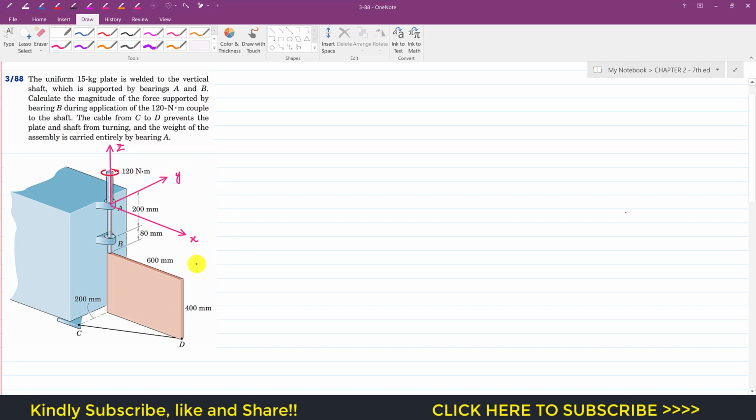Now the first task in this problem is that we have to find the Cartesian vector representation of the tension in this cable. So let me represent the tension we will have if I cut this rope. We will have the tension in this cable, and that tension is going to act in this direction. Let's say this is represented by T. This is the T vector. So T vector is always equal to the magnitude of T times the unit vector from D to C.